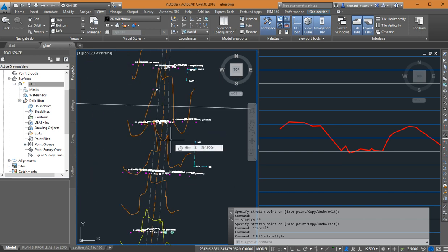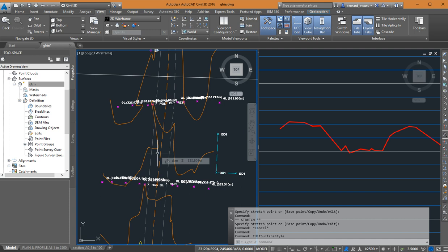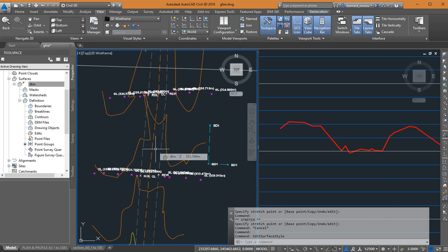Please, do you all have it? Okay, so quickly let's add the road edges as break lines. Then we also try and label the contours and try and see if we can also change the contour intervals. Then we'll be through with the surface. There are so many things we can do with the surface. Maybe tomorrow, as a recap, we'll try and see if we can recap where we ended and build upon it. Please, are we okay? Very good.